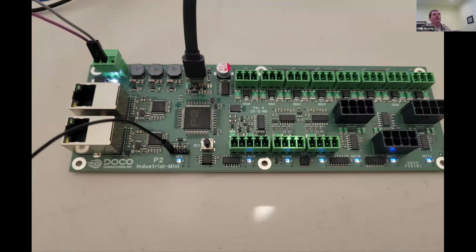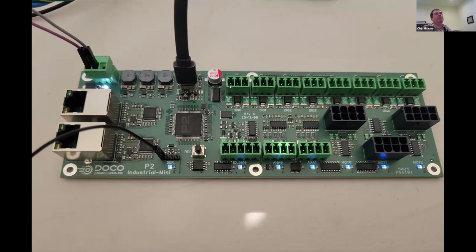They don't need to be nanosecond tight, like the motor control stuff needs to be. These are signals that might control the H bridge, biasing these digital IOs, or controlling the mux for the analog. So we realized those over HC74, HC594s, and 165s.